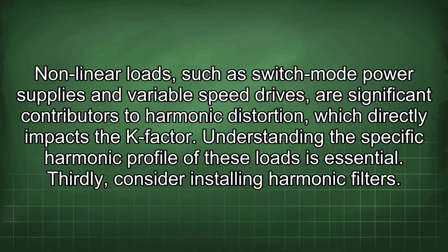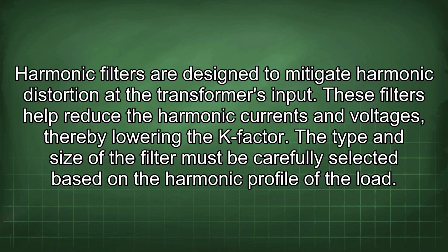Thirdly, consider installing harmonic filters. Harmonic filters are designed to mitigate harmonic distortion at the transformer's input. These filters help reduce the harmonic currents and voltages, thereby lowering the K-factor. The type and size of the filter must be carefully selected based on the harmonic profile of the load.